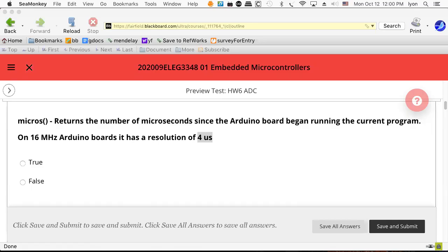That's weird. 4 microseconds, and then raise it to the -1 power, I get 250,000. So that's 250 kilohertz. So this has something to do with some other timer that's trying to give us information about elapsed time. This micros is really not as accurate as you might think.